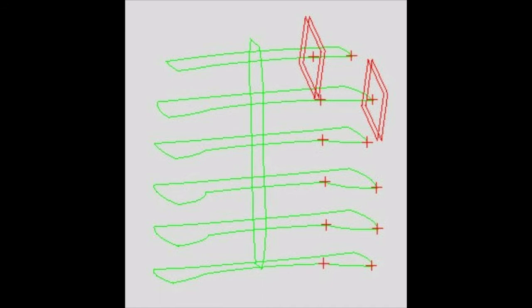Now trim the bolster curve to the new plane and then create a point on the end of this trimmed curve. See the image on the screen. We have trimmed the curve. Now the limits of the bolster surface can be created.